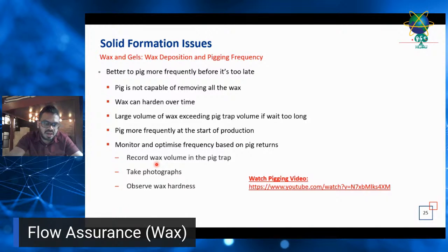We need to make sure that the operator records this wax volume in a spreadsheet for every pigging activity, so that this can be used later in the wax modeling to tune the wax deposition model in OLGA. Instead of using cold finger data, this is much more reliable, because the cold finger data, if you notice, is a rotational based flow. So we need to convert that.